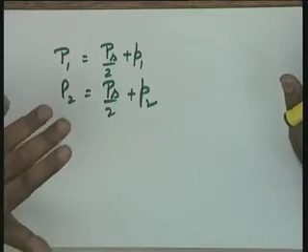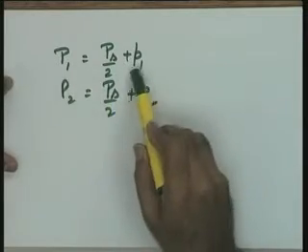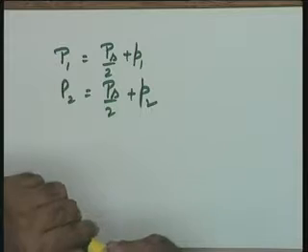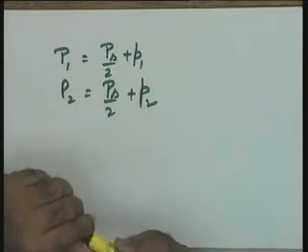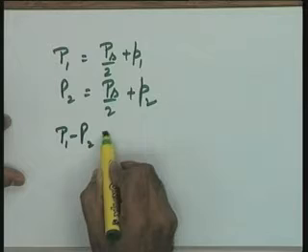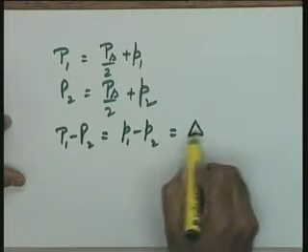Whether P1 is greater than P2 or less than P2, it depends upon the load induced pressures and the movement x you are going to give. So, for me p1 and p2 are algebraic variables, and I am taking P1 is equal to Ps by 2 plus p1 and P2 is equal to Ps by 2 plus p2, so that the net pressure across the power piston is P1 minus P2 is equal to small p1 minus small p2 is equal to del p.